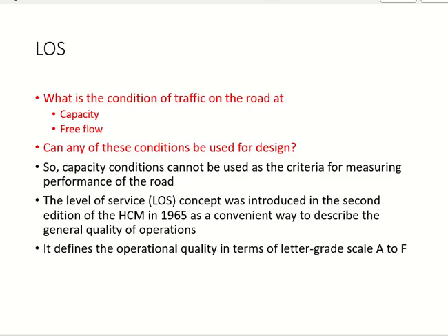But if you want to increase the capacity to avoid traffic jam, you would apply a safety factor to the capacity. Right now we are going for the design, so there is no capacity increase right now. The increasing will come later, right? I designed the road, now there's traffic jam, I will try to increase it. That will come later. But right now I'm just designing it. So the thing is, you have demand, and now you are going to design the road. You want your demand to be less than the capacity, right? How much less? Not free flow, something between, right?